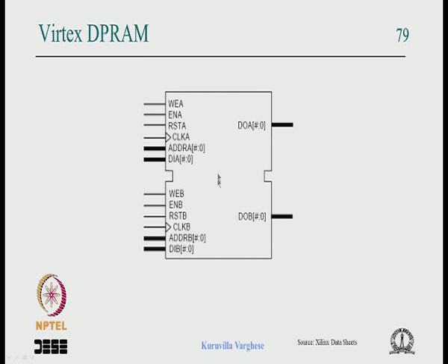The address goes as a select line of the mux, and the appropriate location is muxed to the output. And similarly the input goes parallelly to all the flip flops, but this address line will clock the correct location. So there is an address decoder which enables the clock to the input of the flip flop.